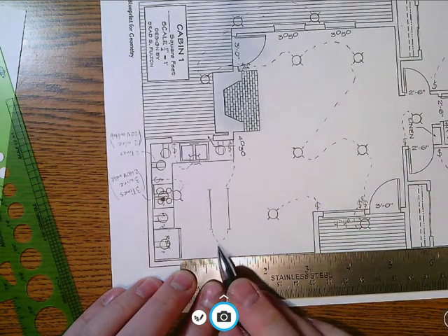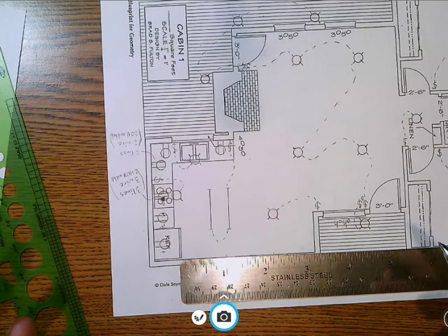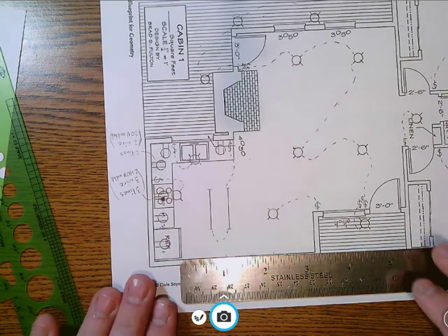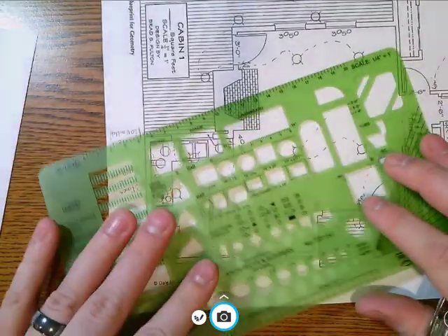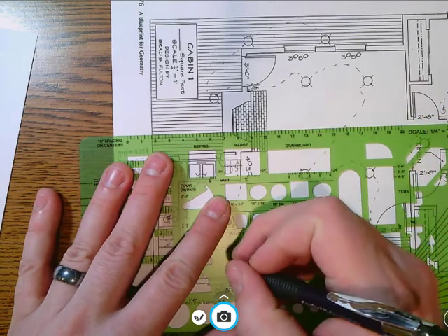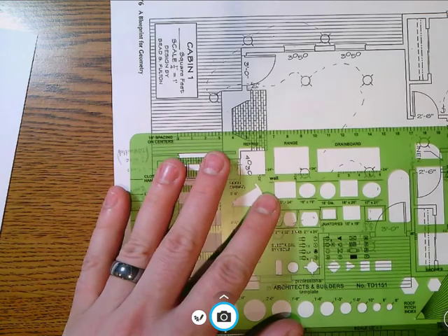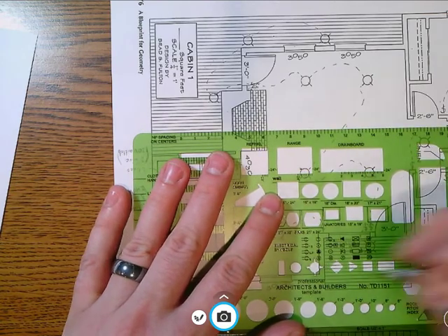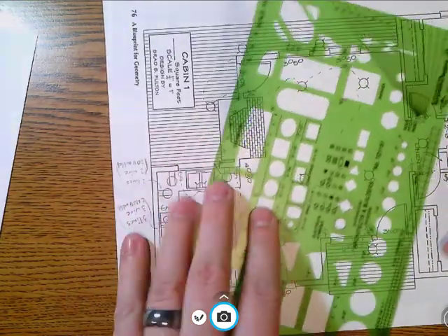This one would be more designated for the kitchen. This one would be more designated for the dining room. And like I said, since it's over 12 feet, we can't cover the whole thing with one outlet. It might seem a little bit more than what's really needed, but you also have to be to code with that general layout.